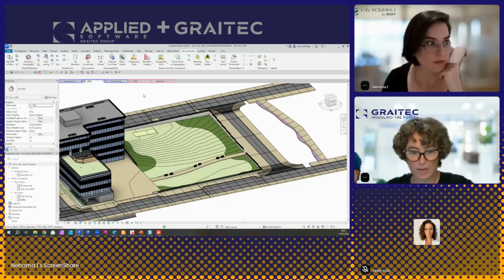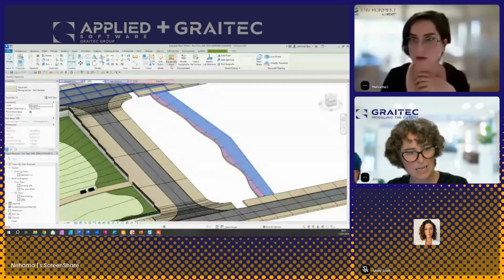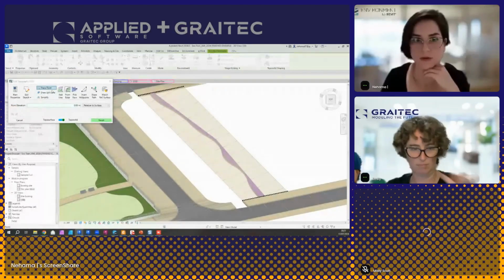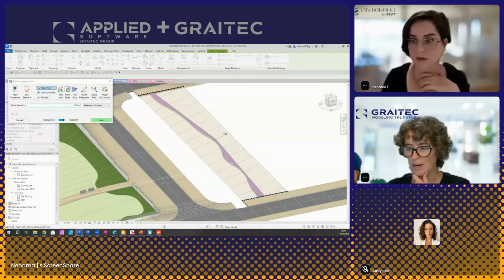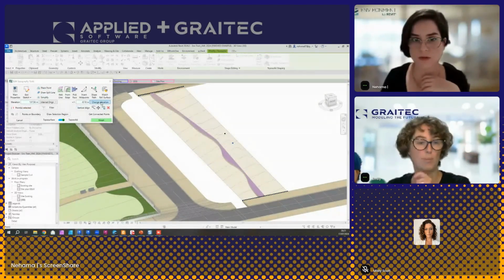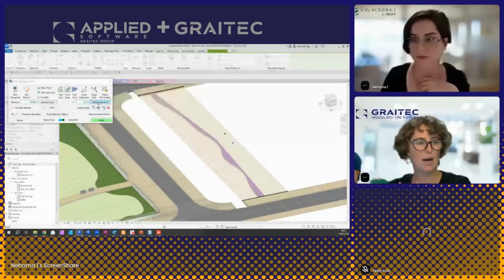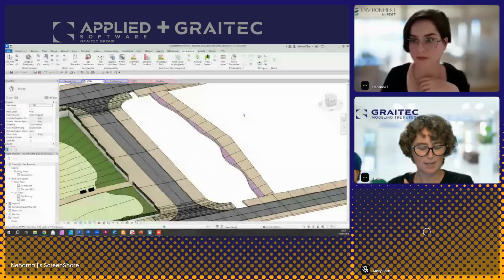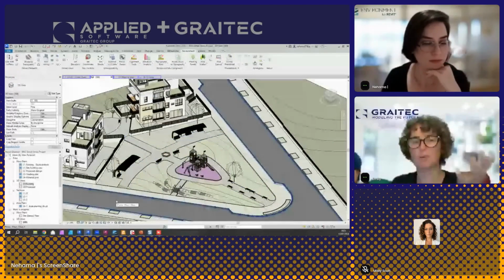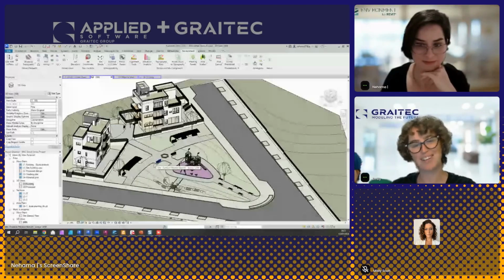You're going to add points to that. So in a few of the screenshots, we'll get into specifics. There are individual points that if you really need to place something at a specific elevation, you can add a very specific point to your reference surface or your actual topo solid. And just in case anybody doesn't know, topography, topo surfaces happened in 2023 and before, and 2024 started topo solids. So we'll try and keep our terminology straight there, but there's a bit of a mix in some of the demos we're using depending on the version we're in.